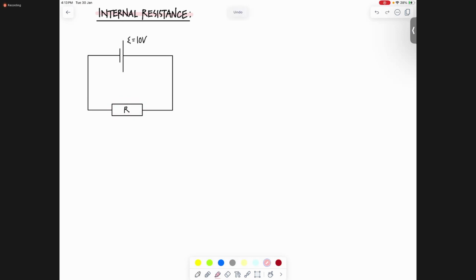10, right? Cannot, because according to which law? The Kirchhoff voltage law. What does the Kirchhoff voltage law state? KVL: the sum of EMF in a loop is equal to the sum of potential difference in that loop, right? So if I create a loop here this way or that way, whichever way, there's only one EMF here, which amounts to 10 volts. And there's only one PD here, which amounts to 10 volts as well.